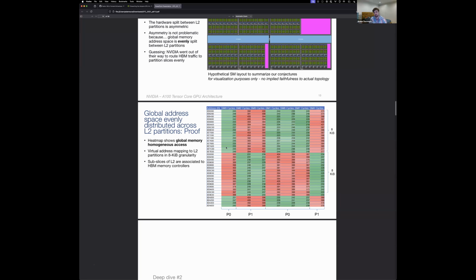And each SM is only responsible for a part of the memory that is on its own side of the GPU. So this requires it to be a one-to-one read-write. If it's not one-to-one, you couldn't do it for both reads and writes. In theory, you could do something crazy like this for a tensor core matmul, just for one of the two input matrices. It would be kind of interesting to get it to work.